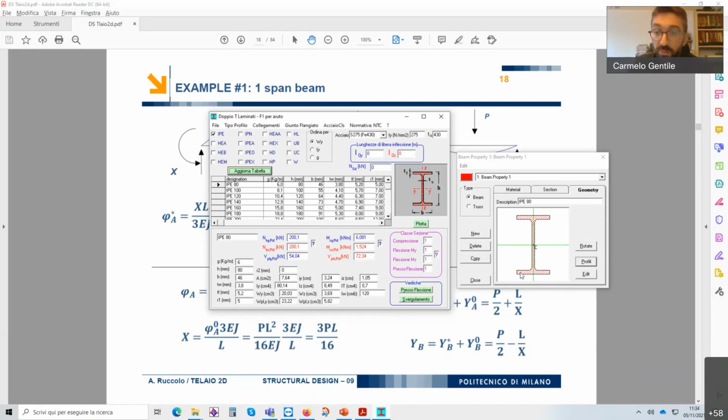With the two flanges, which are smaller than the web. If we untick IPE, okay, let's stick to the IPE. In this page, in this second table, we can see all the properties. G is the weight, the linear weight, so kilograms over meter. So what is the weight of 1 meter of this beam? The height, obviously, is IPE 80. It means that the height is 80 millimeters.